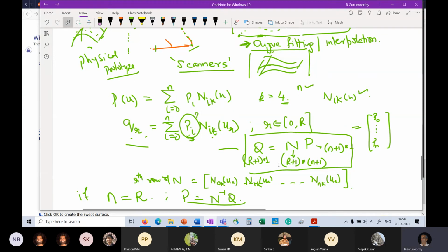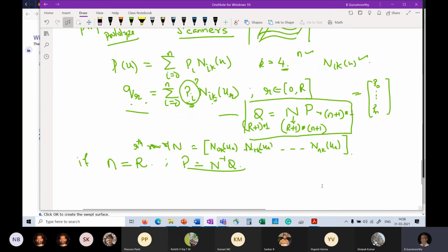Now, n equals r is possible if r is a small finite number, meaning if I give 10 points on the curve, then I can choose n to be 10 without difficulty, and I can solve this exactly. Those of you who have used CAD systems will note that in most CAD systems, when you define a spline, you define it by picking points, and the system will generate a curve like this on the fly. It is exactly solving this problem.